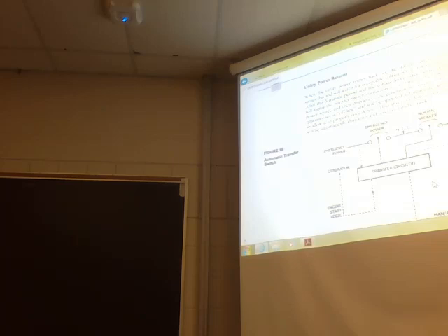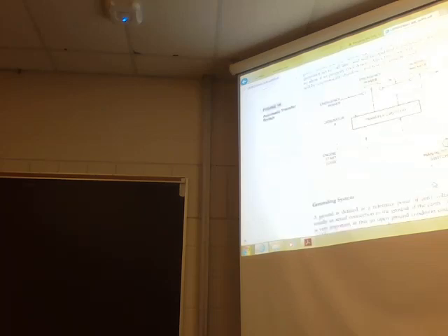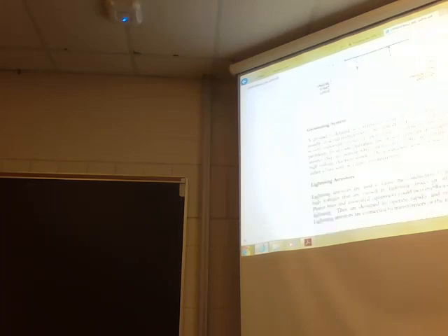A ground is defined as a reference point of 0 voltage potential, which is usually an actual connection to the ground of the earth. The need for grounding is very important in that an open ground condition could present severe safety problems to anyone operating the power generation equipment. Grounding assures that any person who touches any of the metal parts will not receive a high voltage electrical shock. The conductor used for this purpose is either a bare wire or a green insulated wire, and it will be copper.